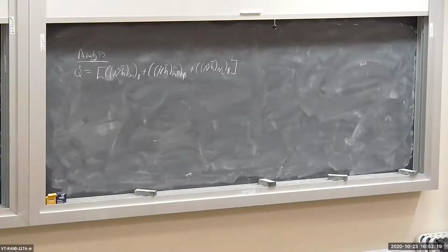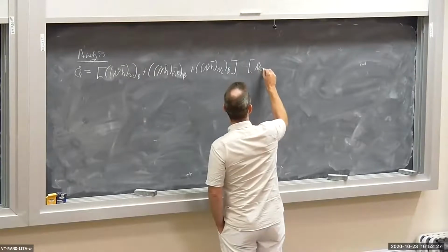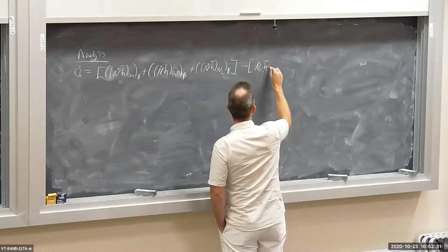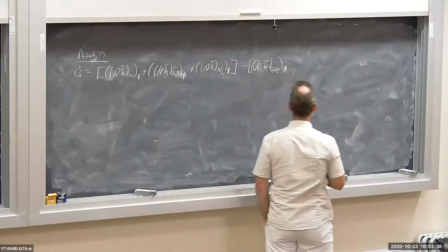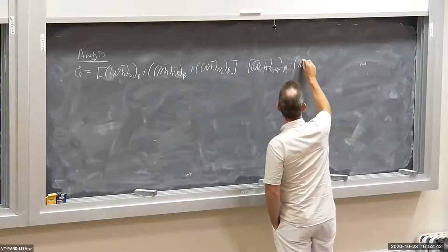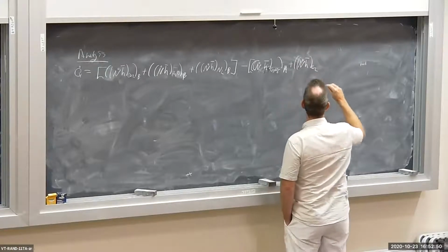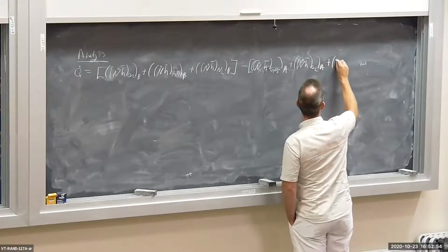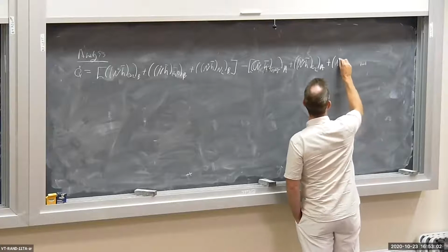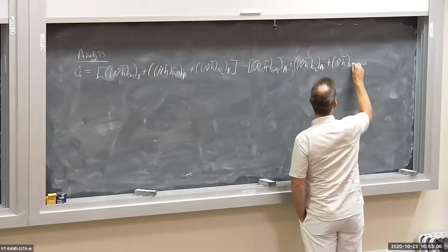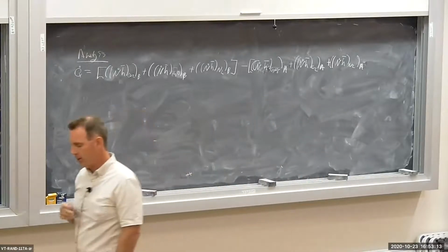And then I have the inlet flows. So I have minus N dot C3H8 H bar, C3H8, evaluated at the inlet or the reactant side, plus N dot H bar for the O2 component, evaluated at the inlet, plus N dot H bar, the nitrogen, evaluated at the inlet. Okay? So that is our energy balance.